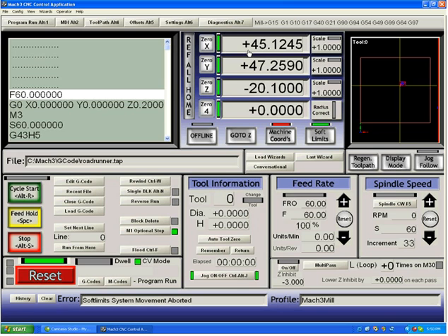When someone tells me that their DRO indicates they have moved 1 inch, but they have only moved a half an inch, I know what the error must be, because I know that a DRO is always accurate. Its code is not attached to Mach3 in any way in terms of how it changes. A DRO changes only if pulses have gone out the printer port, unless you have referenced. That is the only thing which will change a machine coordinate.